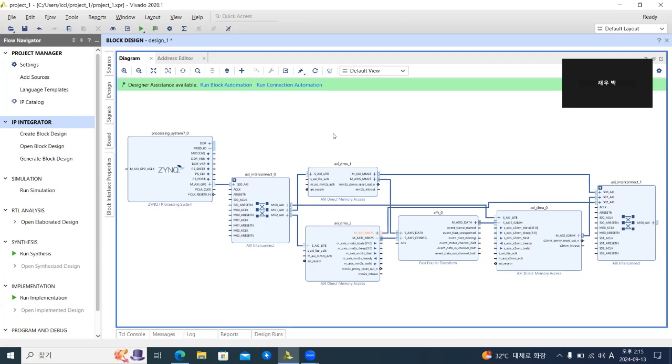Okay, sure. The first AXI interconnect is there so we want to make the CPU talk to the DMAs. The second AXI interconnect does the exact opposite. It lets the DMA be able to talk back to the CPU. So that's why the first AXI interconnect has one slave and 3 masters. Instead, the second one will have 3 slaves and 1 master.